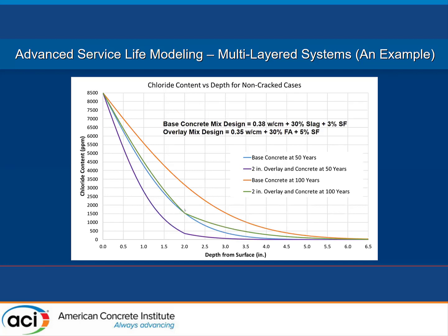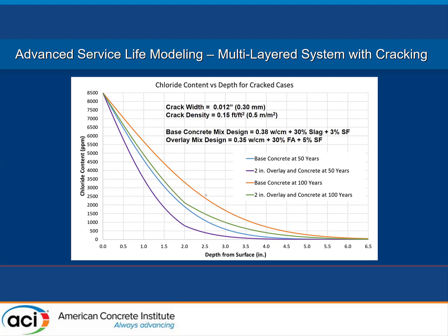That was kind of shown by some of the results of Doug on some of the silica fume decks, where you got very good lifetimes, but if you want to get to 100 years, you're going to need to do something else. So cracking moves all these curves up. You're going to have less time, you're going to need more cover and more help. So you can adjust the cracking.